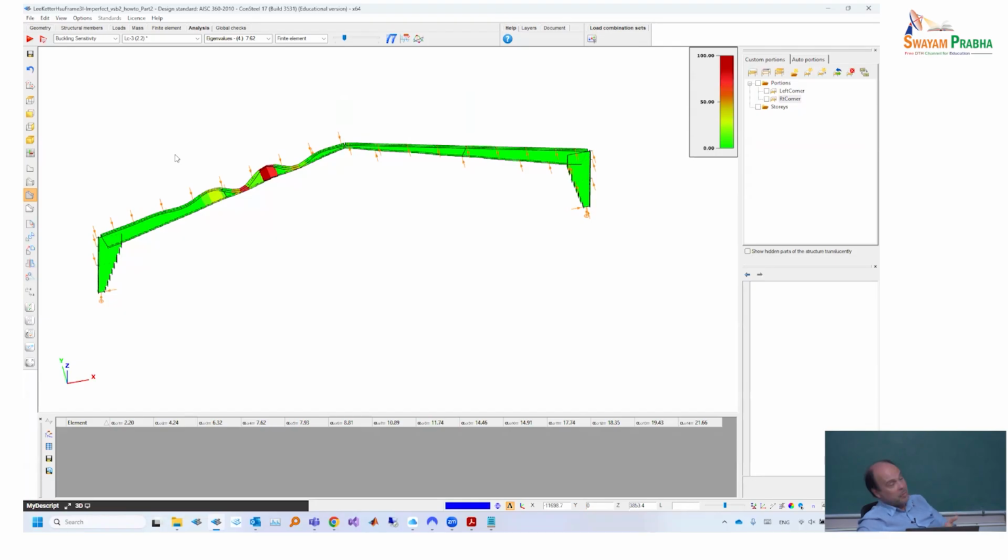So what we do is that we take the buckling mode, multiply it by 1 millimeter, change it into a deformation, and for each of the finite elements we calculate the associated deformation energy. We don't know exactly how many joules it is, but it doesn't matter, because again we don't know the scaling, and the physical value is not relevant.